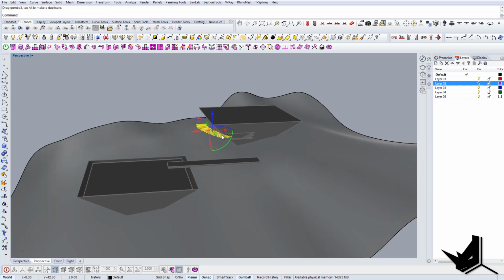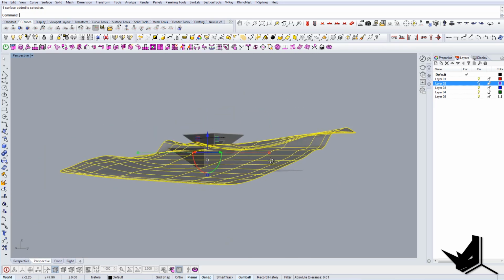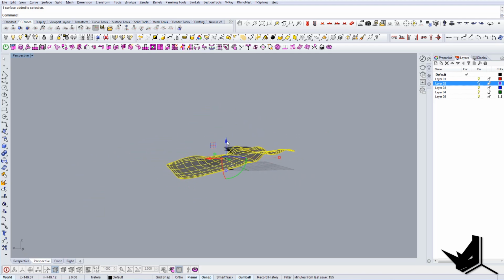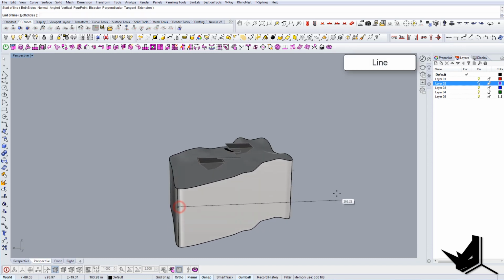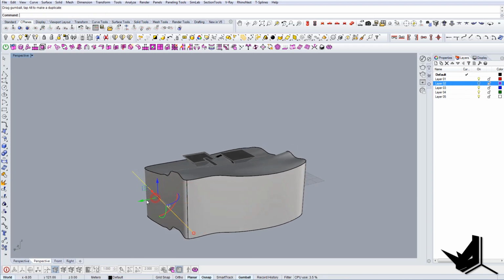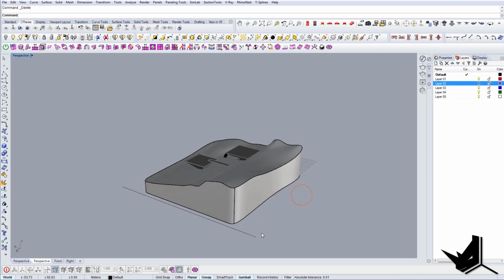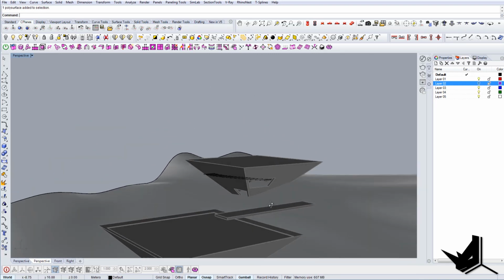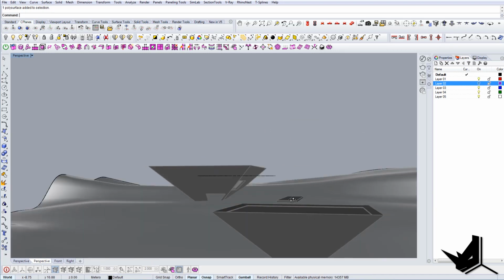And before doing that, of course, I can create this as a solid if I want. The best way to do this is just extruding it downward, and I can actually cut it like so to get this as a ground. So I can use it to present it if I want for the diagrams or whatever I want. So I now have this as my terrain, and I will use some kind of image like this or the angle like this to show the project.